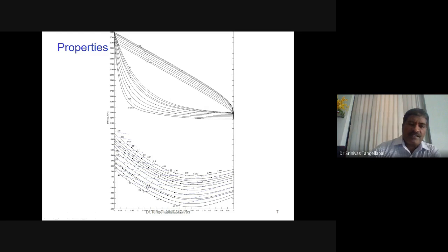As per the region, I classified 5 regions, and the properties like the temperature-concentration chart and the enthalpy-concentration chart are given. In case the fluid is a mixture of liquid and vapor, I told you the auxiliary curve has to be used, starting from the saturated liquid state at a given pressure. The loop is prepared at one particular constant pressure.